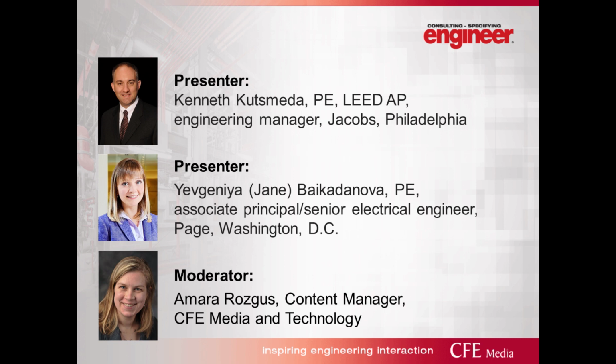Yeah, I would definitely recommend getting the available fault current from the utility and running some kind of short circuit study before you start purchasing equipment, because it can have a huge impact at both low voltage and medium voltage, depending on what the rating of the equipment is. Oftentimes, by the time it gets to a contractor, you've already purchased a lot of the equipment. So you want to make sure that at least the fault current rating and a preliminary short circuit study are done during design, before it gets to construction.